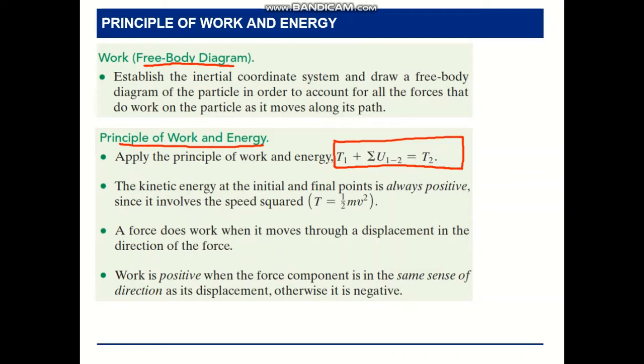So we need to keep in mind that a force does work when it moves through a displacement in the direction of the force. That is already explained. And work is positive when the force component is in the same sense of direction as its displacement. Otherwise, it is negative. So we take the force projected onto the path, right? If the work is negative, that means the force is acting in the negative direction, like a friction force.